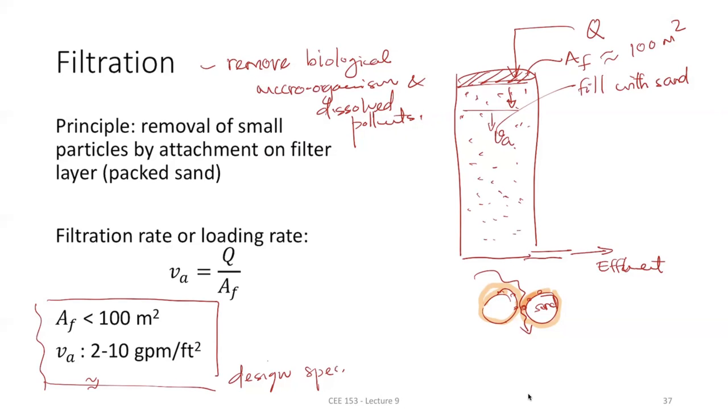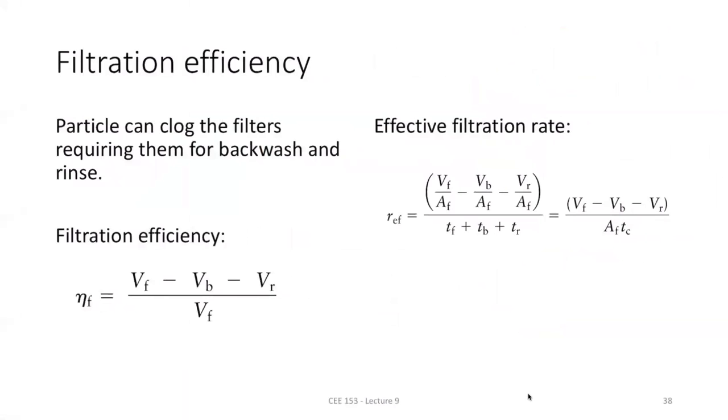So you want to remove those particles. What you do is reverse the flow. You do backflushing so that you can disperse or remove all the sediments or small fine particles that deposited, and you remove that volume of water. That means that much water we cannot treat because it is being removed. Then you can inject again, now that the clogging has been removed.